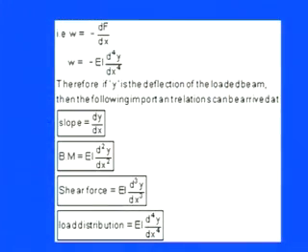The corresponding shear force is E into I d cube y by dx cube, and the rate of loading or load distribution is E into I d4y by dx4.